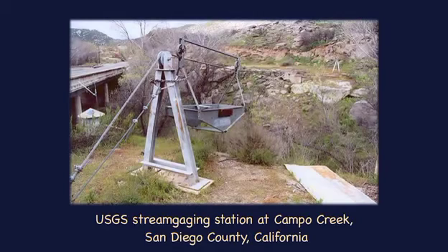These samplers are designed to assure that the velocity in the intake nozzle is nearly equal to the local stream velocity. Samples may be collected by wading in a stream, by hand from a suitable support, or mechanically with a cable and reel setup.